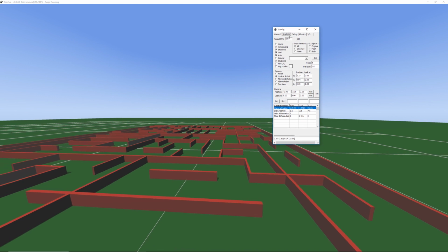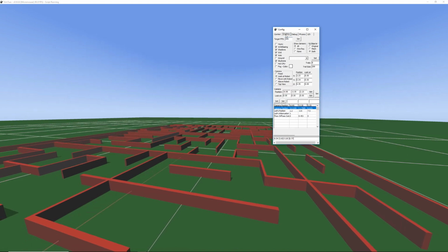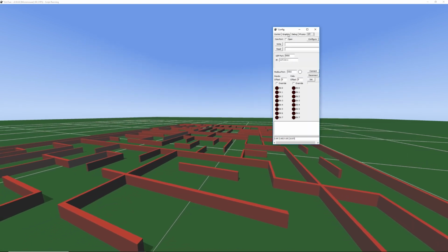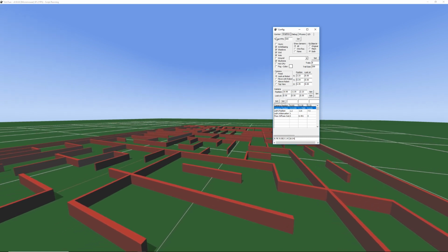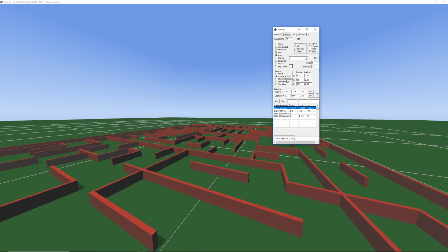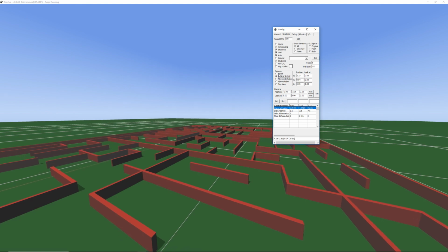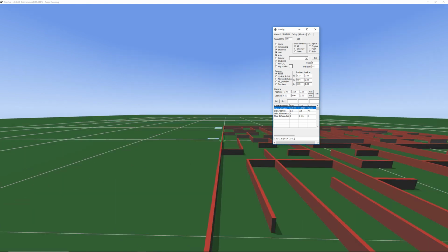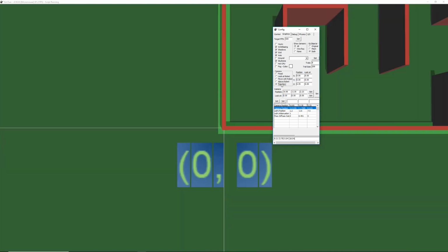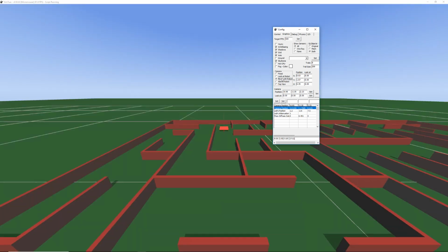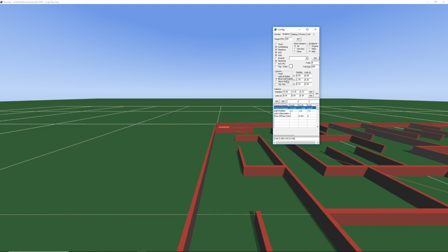And right here, go to this second tab, where you can see tabs: control, graphics, debug, physics, IO. Go into graphics, and you're going to change your camera position to move with robot, right here. You can see the difference looking at the robot. I can choose a fixed position, but I can say move with robot. I can do above robot or top view, but I'm going to do move with robot. And now the camera is going to move according to the robot's movement.